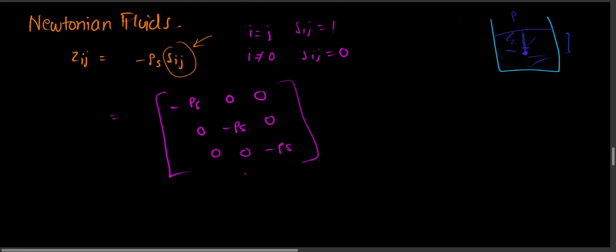Okay, so this is Pascal's notation, and this is for hydrostatic, which is like normal sitting fluids which are not dynamically moving. And when they are not dynamically moving, we can assume the shear stresses, these non-diagonal stresses, to be 0. So we can do that. But of course, in our case, we are learning about hydrodynamics. So we can't really assume these stress vectors to be 0, and therefore we need to solve it.